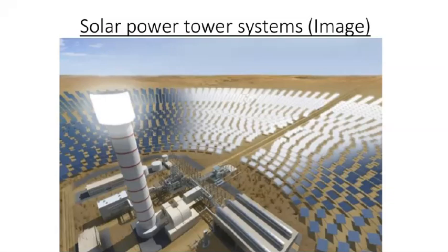So the system must be very precise in order to ensure that the sunlight is really focused on the top of the tower. It is here that the absorber is located, and this is heated up to temperatures of thousands of degrees centigrade or even more. The hot air or molten salt then transports the heat from the absorber to a steam generator, in which superheated water steam is produced, which drives a turbine and electrical generator.